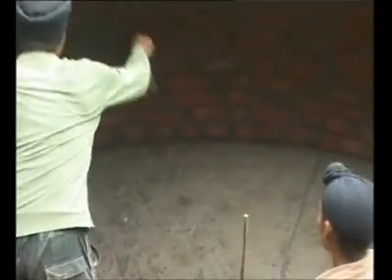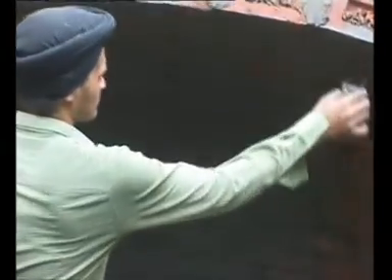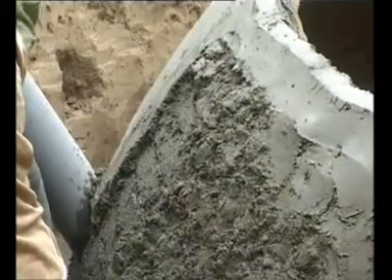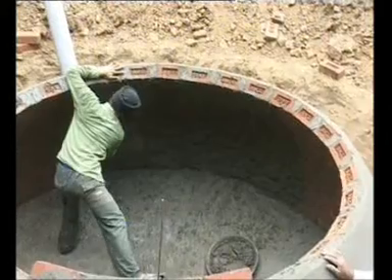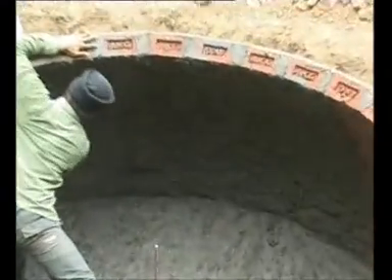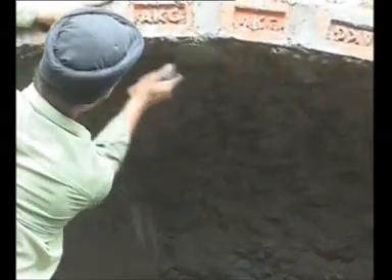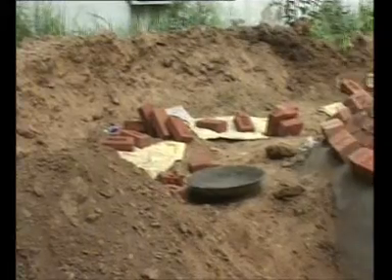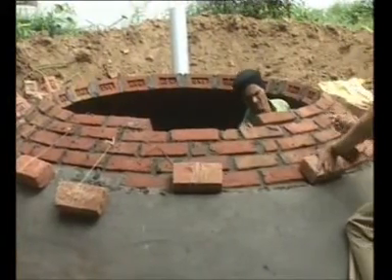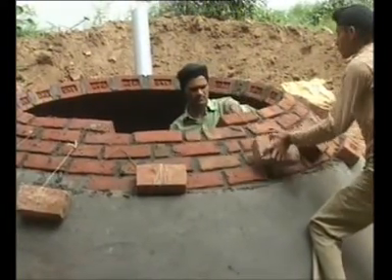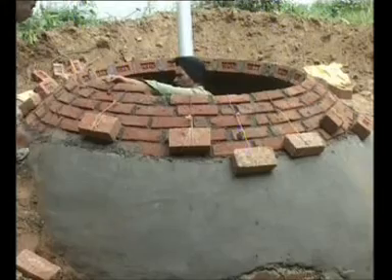After the construction of 15 layers, slurry of cement is applied for plugging any possible pores. After this, a 1-inch layer of plaster is applied on the outer surface. Similarly, 1-inch thick plaster in 1:3 mortar mix is done from the inner side. Above 15 layers, another 10 layers are laid by using a 1:4 ratio of mortar mix. Counterweights are also applied for the stabilization of the wall.